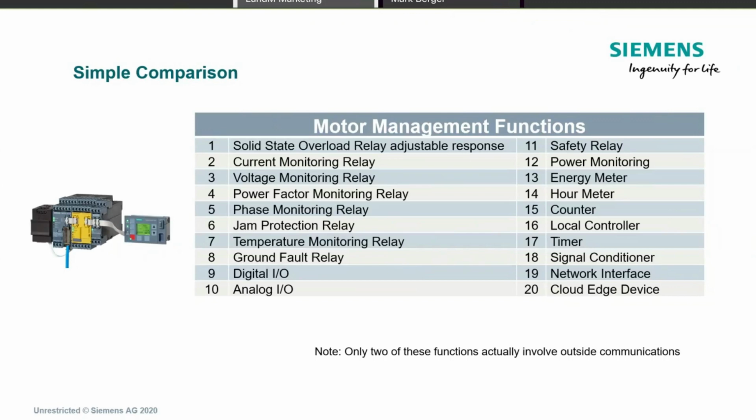that there was a means of doing a jam protection and being able to click and do the logic for it. And then in addition, across the way, I was able to count how many times that jam protection was energized and reversed. And if it continued to jam after 2 or 3 times in a time period, then that's when they called in the operator and let them know that they needed to look at this hammer mill to figure out what's going on.